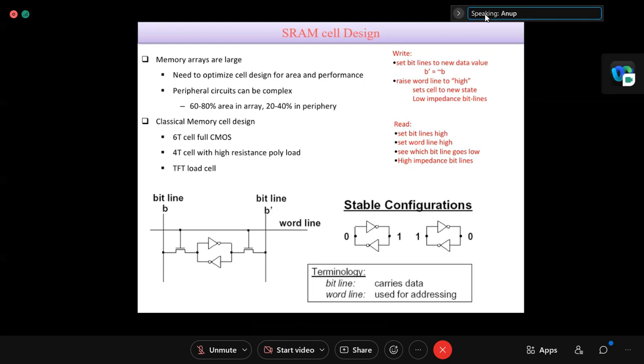Now, let me make it very easy. Y equals AB. Just now I have given you one idea that most optimized Boolean functions are represented by gates. So Y equals AB, one AND gate. Now Y equals A dot B dot C means 2 AND gates, or one can say a 3-input AND gate. If two-input AND gates, then 2 AND gates are required.